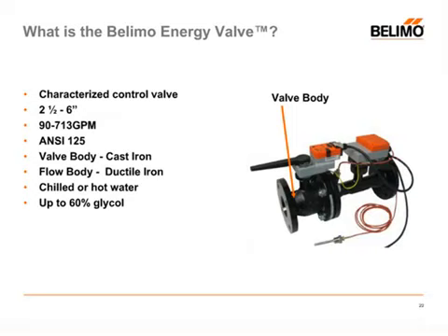Now you may notice here that there's this flute-shaped pipe. This is actually for our flow sensor. The reason it's shaped like this is because we require 5 times DN size as an inlet to achieve what we call non-turbulent flow, or laminar flow. And that allows us to stabilize the flow coming into the valve so we can get a nice, smooth, steady flow through our flow sensor to calibrate for modulating the valve. So that's the valve body itself.